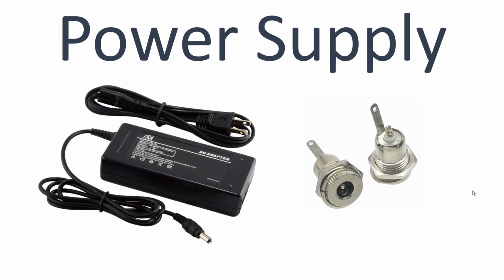Then, of course, you need something to plug it into. Now, the reason that I like plug into instead of screw terminals is you have less possibility of wires becoming twisted, fraying, and little flags sticking out and shorting to the other side of the supply. Now, I typically use 2 of these bulkhead connectors, and they are wired in parallel internally. That way I can plug into either one, and if I want to, I can have a jumper that goes from the box that these 2 are mounted in to another box with another bulkhead connector into it. That's typically how I build my field device simulators.